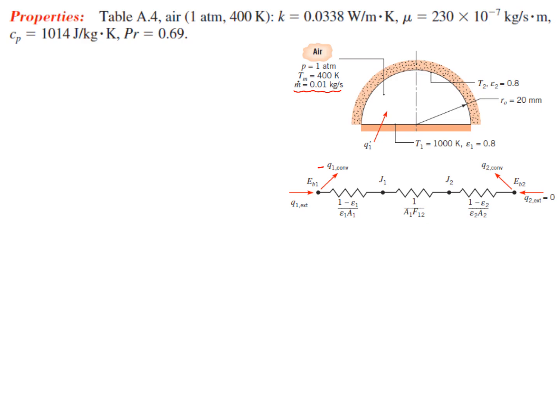So in both of the cases, forced flow, I do have to calculate my Reynolds number, to see if it's a laminar flow or a turbulent flow. So for that, I will have to write rho v for the velocity, and then I have this Dh, which is the diameter for cases where you have a tube or a duct that does not have a circular cross section. So in a case like this, I don't have a circular cross section. I have to come up with an equivalent diameter for the cross section. So I'll have to first figure that out before I actually do anything with this Reynolds number. So let's just figure that out first.